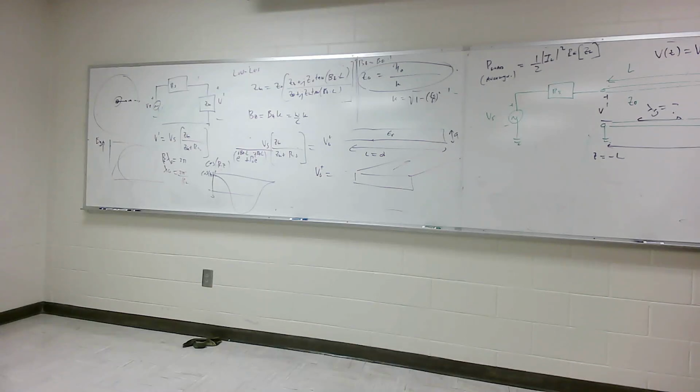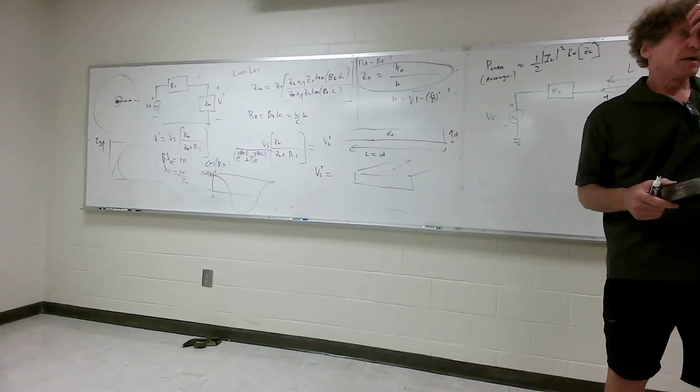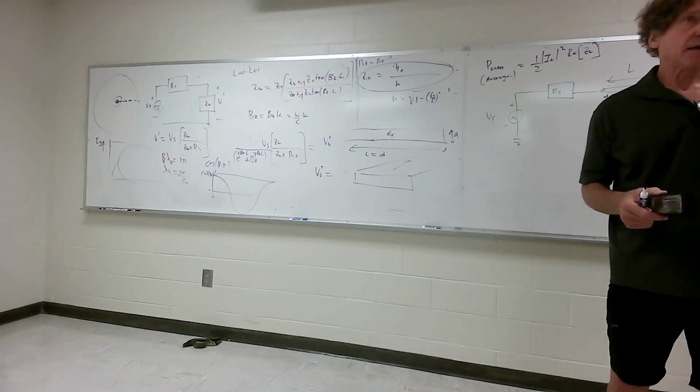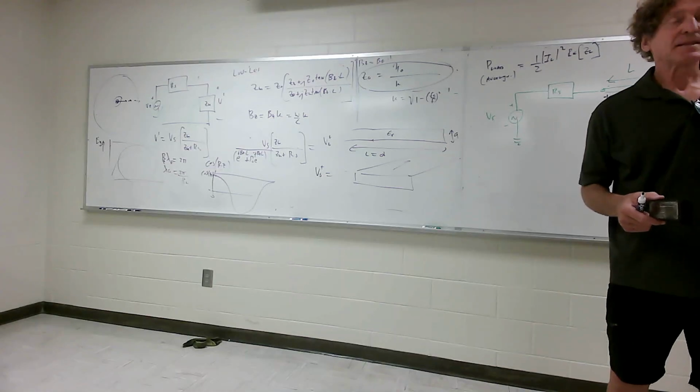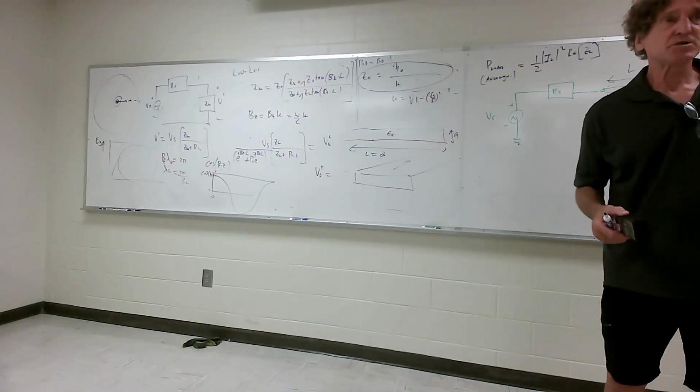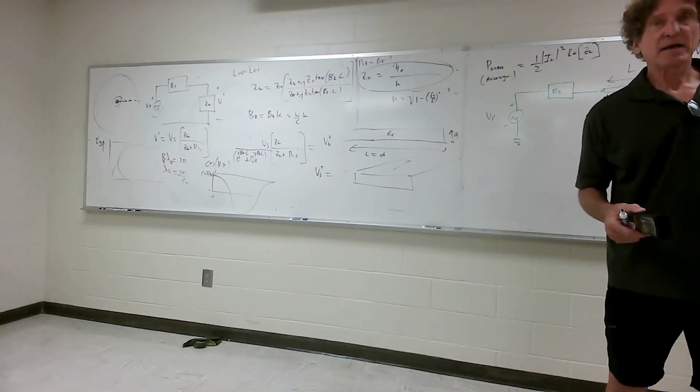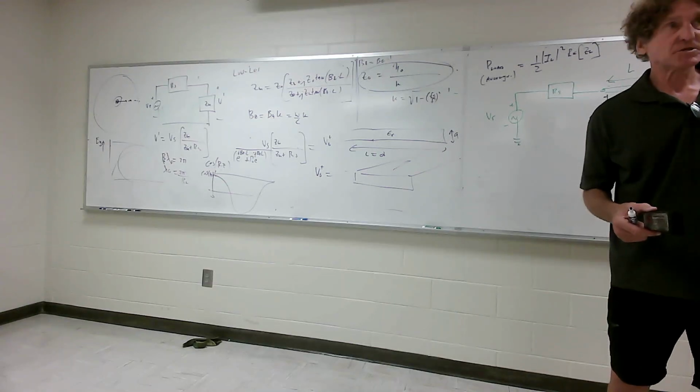That's what I want to do today. I actually want to tell you that there's a lot more I could tell you about this, but optical fiber is on page 407, and I want to first give you my perspective on this. The real reason optical fiber is so important is not the power they can handle, not that at all, but the attenuation is so extremely small, and you can propagate frequencies that are so much higher.